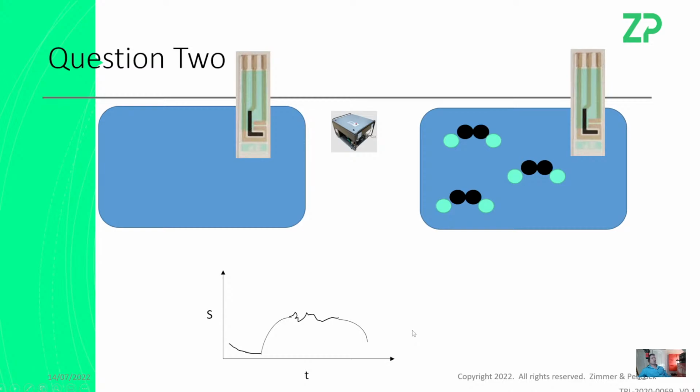I think the concerns are the lifetime of the sensor, and you almost have to have an engineering process where you decide, am I going to have a sensor in here that's for life? But having a sensor in there that's for life, sitting in an approximately 1 millimolar hydrogen peroxide solution, could be a little bit corrosive on the sensor. But it's all about duty cycle. How often is this used? How long is it used for? From the first instance, you almost have to try it, and then in the second instance, you have to think, do I treat the sensor as semi-disposable?